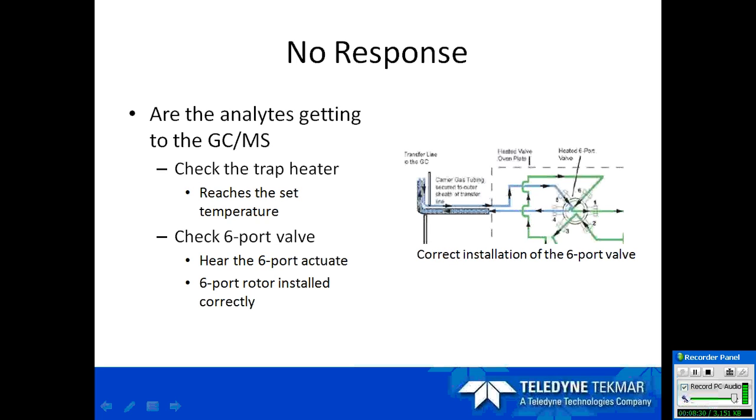The first category that we're going to be talking about is whether the analytes are given to the GCMS. First, with your trap, you want to check your trap heater. Is your trap reaching the correct set point to desorb the analytes off the trap? Also, with this part,